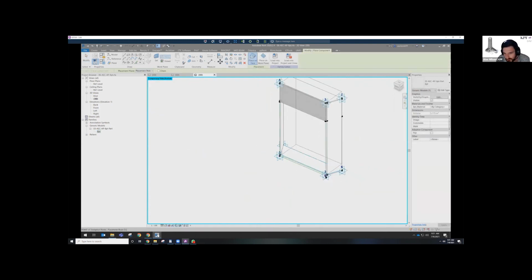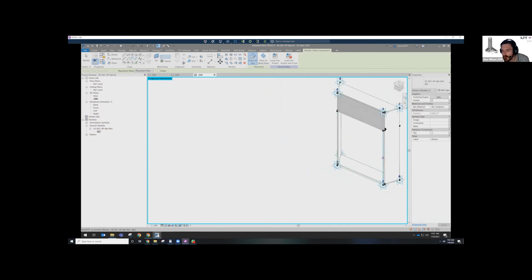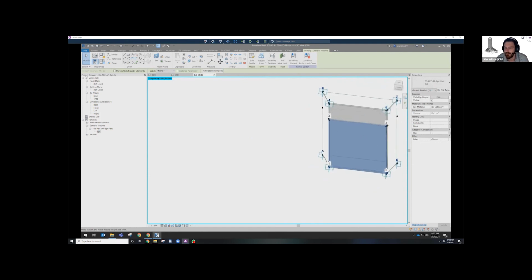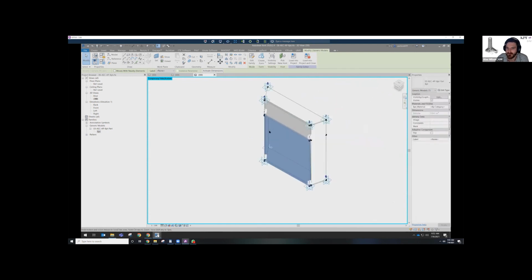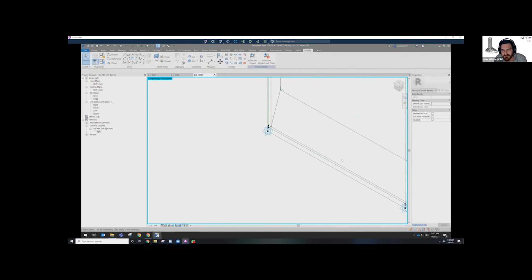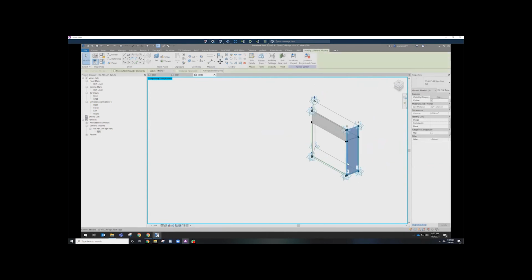But at this point, if I just place my points like so, it's going to create the family and snap it to those points. That was the wrong one, whatever. The nice thing about this is it lives with the outside, so it's very easy to update. But as you load it in, you just need the points. You don't need the reference lines as well. So that's an important distinction with adding additional detail to some of these families. You have a skeleton and then subfamilies just placed on it inside the project.